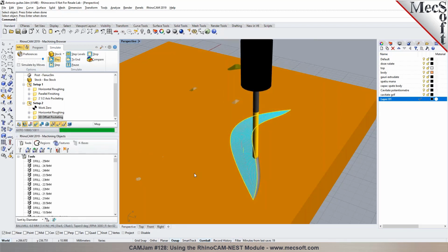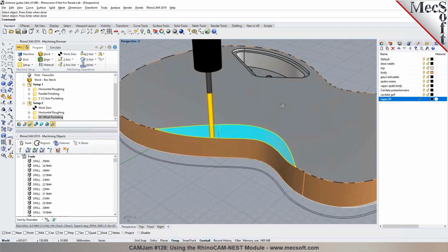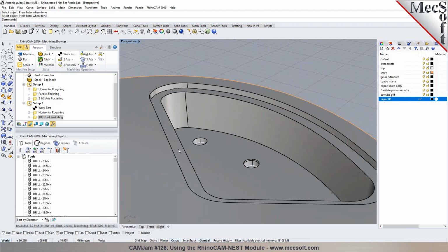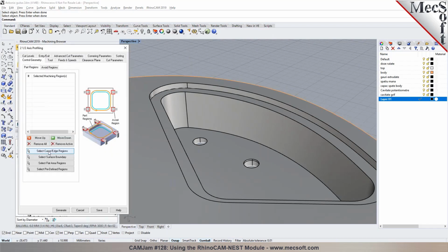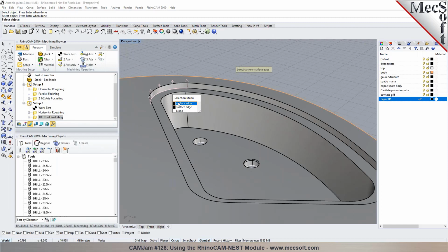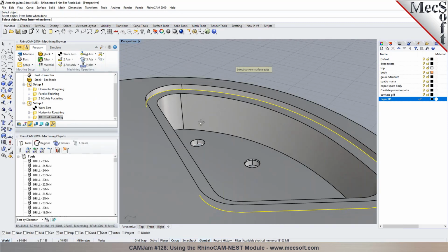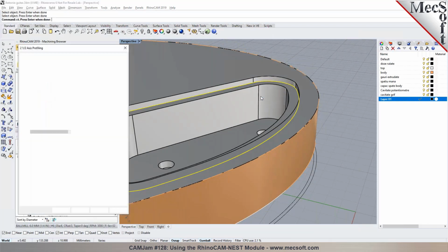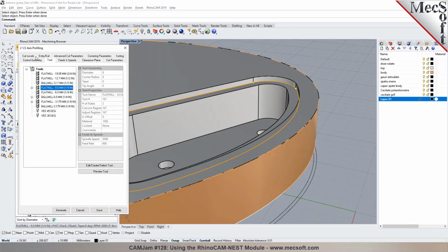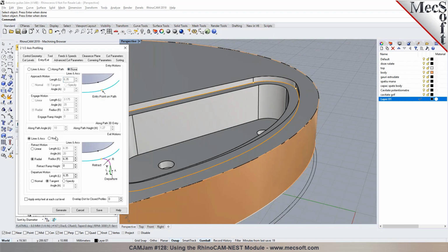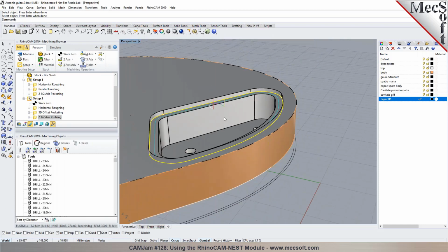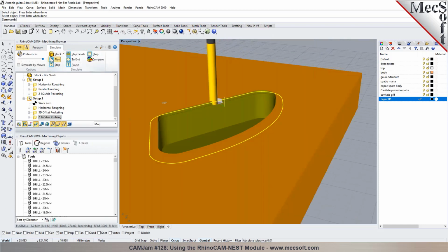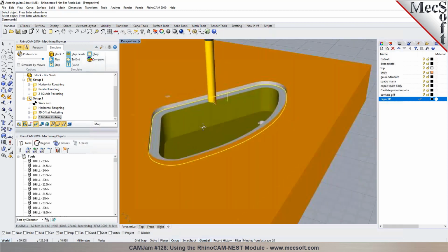And then finally, you want to cut the profile around the part. After you program all of these features, you could add a profile and cut to clean up the profile in here, 2-axis profiling. I would like to cut this step on the part with the flat mill 8mm. And you can choose it's at the bottom, generate it. So that'll give you a profile cut to clean up that step right there.